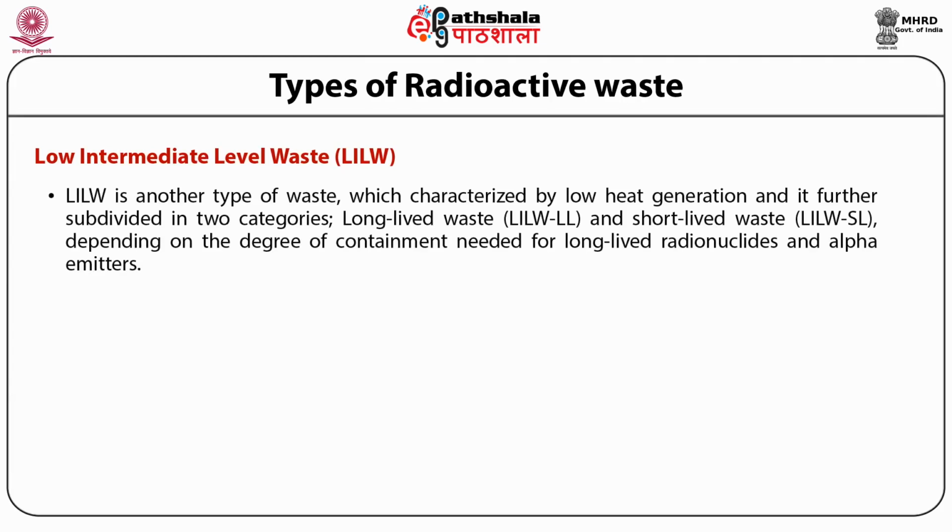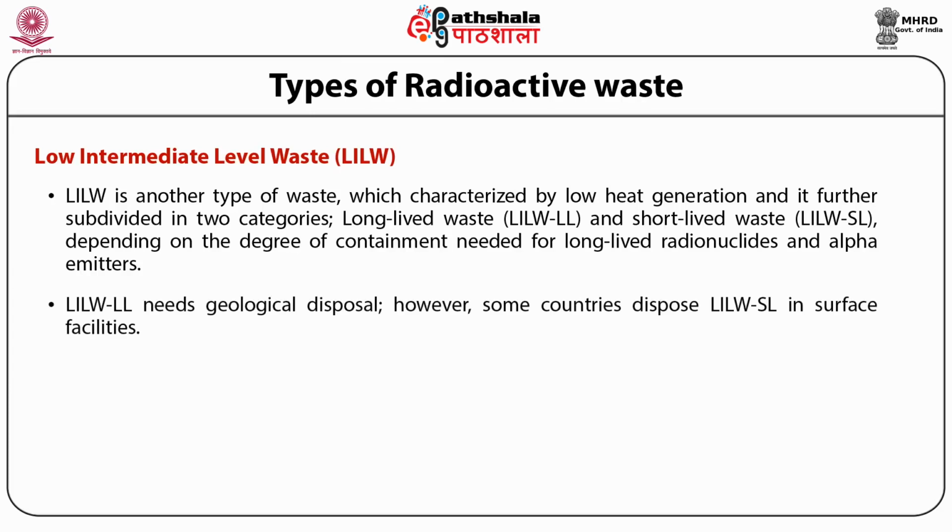LILW is another type of waste, characterized by low heat generation, and is divided into subcategories like long-lived waste, that is LILW-LL, and short-lived waste, that is LILW-SL, depending on the degree of containment needed for long-lived radionuclides and alpha emitters. LILW long-lived needs geological disposal. However, some countries dispose LILW short-lived in surface facilities.